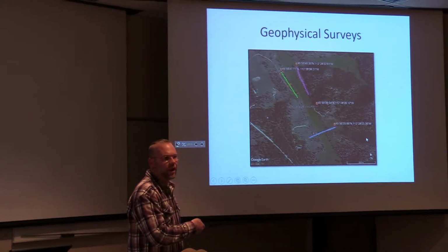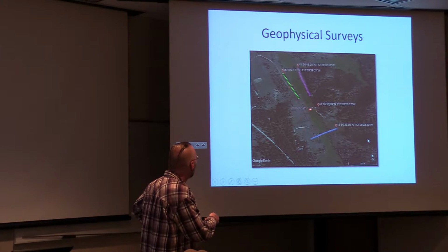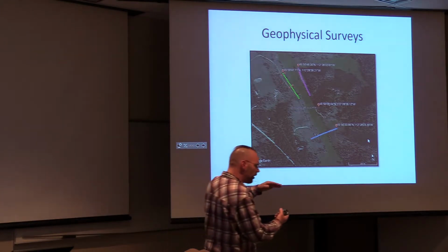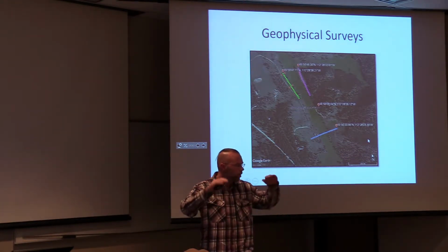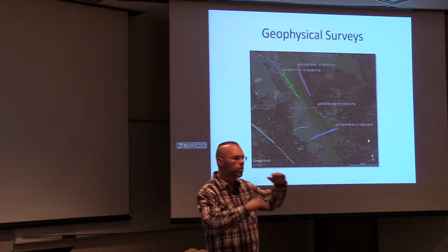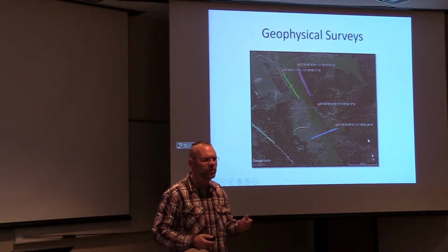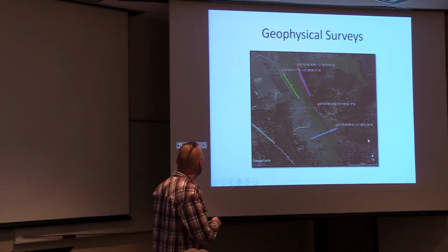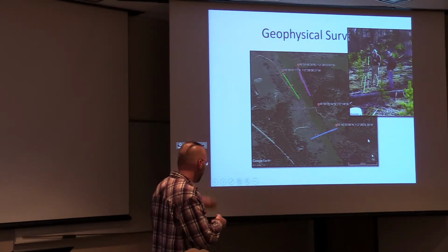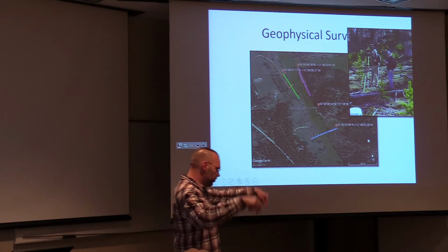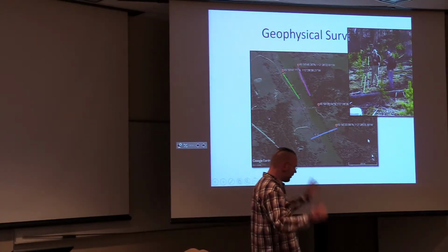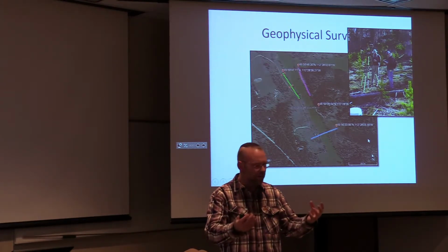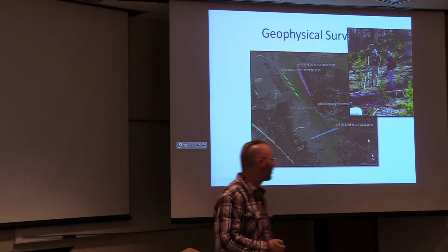It was in May, it was too wet to do the monitoring in the floodplain. He did a line across the road here, and he did a line across the road here. The water table was too high to map out, but we're trying to map out the subsurface geology, and he can go about 120 feet, we'll say. There are the students surveying in all the points. He puts this line out, puts electrodes in the ground, excites the electrodes, induces an electrical current, and depending on whether it's sand or silt or clay, the resistivity is going to behave differently.